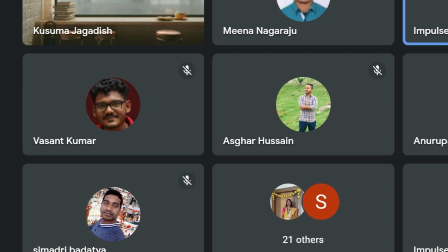There are so many open source libraries like Materials Project and the Crystallography Open Database where some materials are already available and their input parameters are given, like lattice parameters. So that material you have to upload or create, but at least some input you should know. You should have some input parameters for each material. Either you can use the existing material or you can do your own research by putting in or changing some input of your material, like lattice, bond lengths, and alpha, beta, gamma, a, b, c. These all things you should know, and then only you will be able to simulate it.